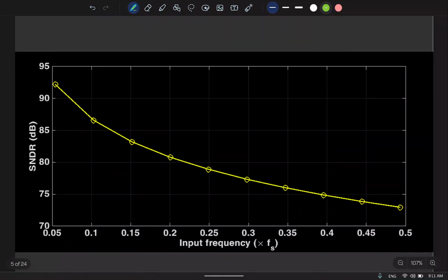So this is simulation results demonstrating that. Again, here I am applying a sinusoid. And remember that when we measure the spectrum using FFT, we always follow the same principle. You decide the number of points. So here I have chosen the number of points of DFT as 1024. My Fs I think is 20 megahertz or 25 megahertz, I don't recollect.